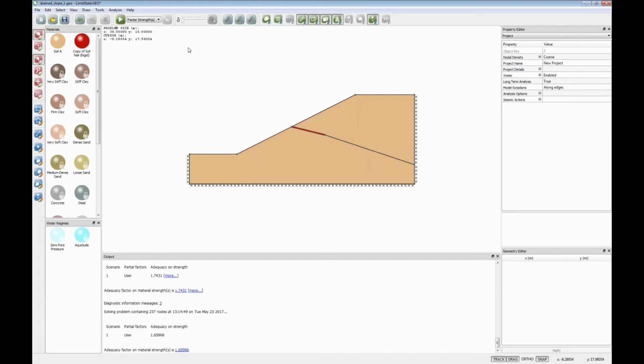It is an idealization, and you'll obviously get some deformations outside those plastic zones because we are analyzing the plastic limit state in those cases. Because of frictional soils, the theory of plasticity that's employed in the software employs an associative flow rule, and those mechanisms may be slightly larger than may occur. Generally, they're still going to give you an indicative place of where the deformations are going to happen.